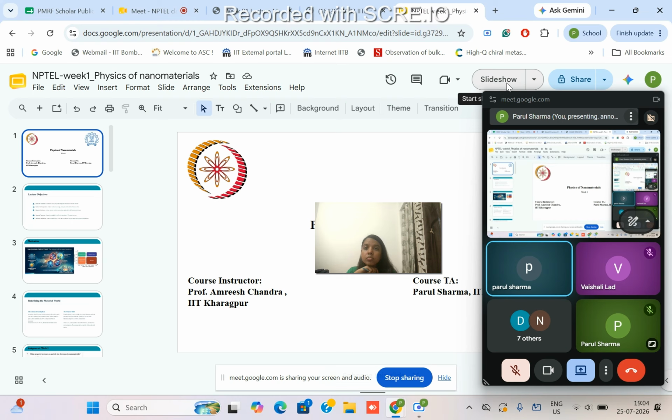The laser will excite the cantilever tip, and the light will deflect. The light will deflect from these sides, and then it will fall on my surface. It will generate a signal that will directly go to the photodiode, and it can give us the AFM image according to the particle size, and we can go up to 10 nanometer only.